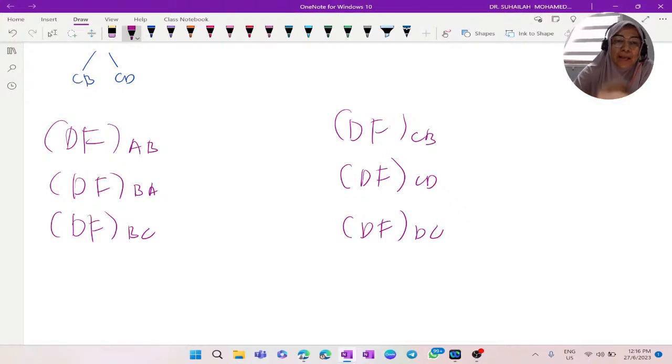AB is the far end, the fixed end. For a fixed end, the factor is 0. Same goes for DFDC, because it is a fixed end, this is equal to 0. Why do we get 0? Because the stiffness will be divided by infinity. That is why the distribution factor for a fixed end is equivalent to 0.